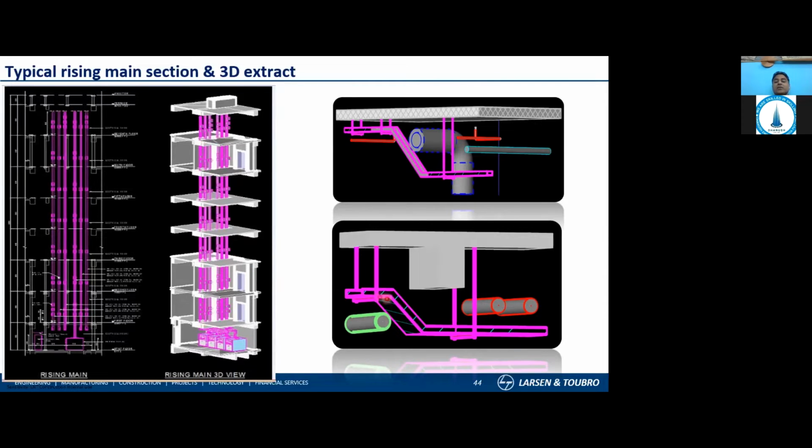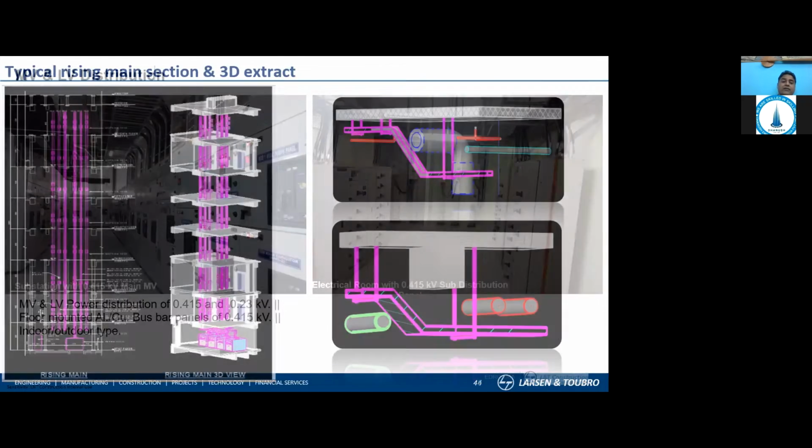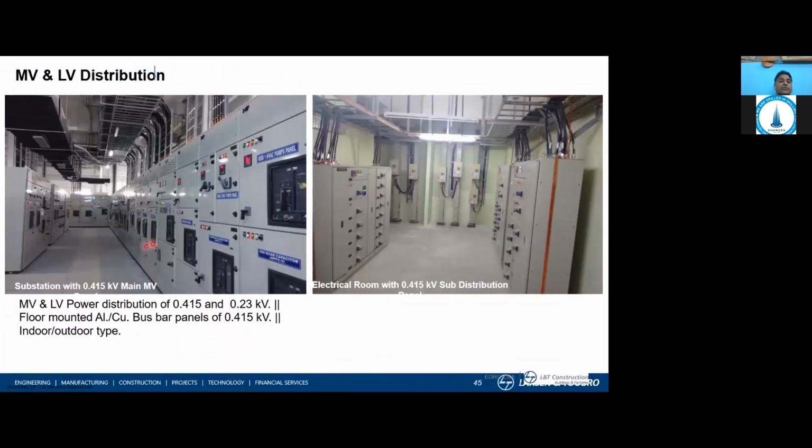Electrical is the most flexible with respect to the cable tray routing, because that can bend. The only thing is I need to take care of the bending radius, and at the same time for the fire, he has to comply with the statutory norms with respect to the detector and the sprinkler coverage. So with these dynamics in place, we coordinate and agree on an amicable solution.